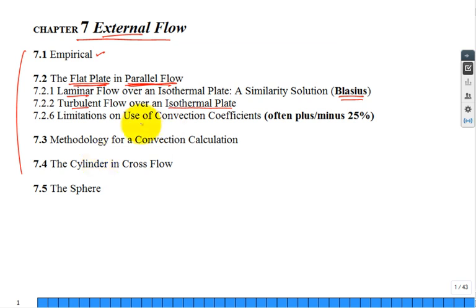Okay, then there are some correlations that are developed empirically. This is analytical/numerical, which is very neat, but then after a point, you just have empirical correlations based on experimental measurements. And whenever you get these, don't think that they're so accurate they can't ever be updated or modified or anything else, or somebody's measurements over here and somebody's measurements over there have to be in perfect agreement. They're typically not. There's a lot of uncertainty in these correlations. Plus or minus, I would say 25% is not unusual, which is a little frightening to students.